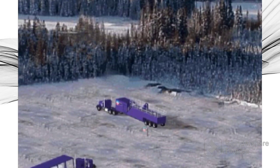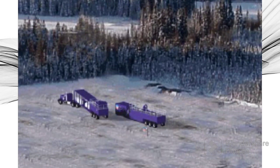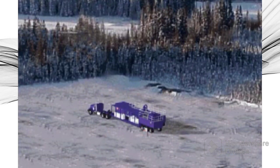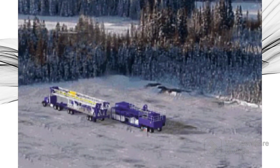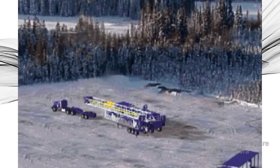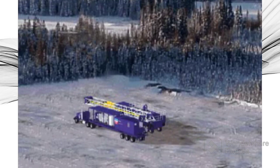Before this is done, the derrick hand lines up the mud pump and starts it to circulate the hole, cool the bit, bring cuttings to the surface, and keep the hole intact. To help keep cuttings from plugging the hole, the mud passes through a shaker that separates the cuttings and brings the mud back to the bit to drill ahead.